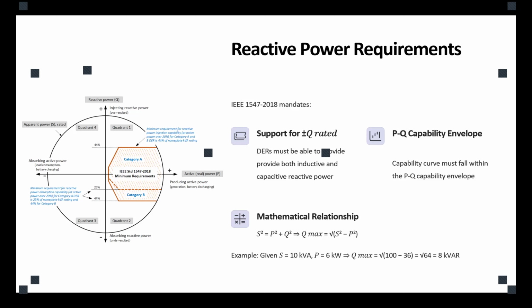The maximum reactive power is basically defined by the limitation of our resources, but we cannot just connect to the grid and simply not contribute to the fault. There is a minimum contribution expected for all the resources. And IEEE 1547, actually, you could see in the graph, defines that minimum contribution or reactive power injection. Are we good?